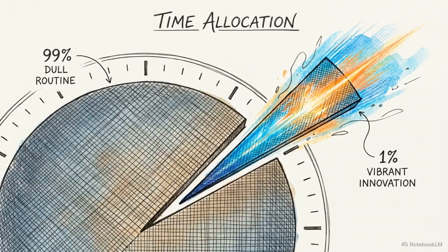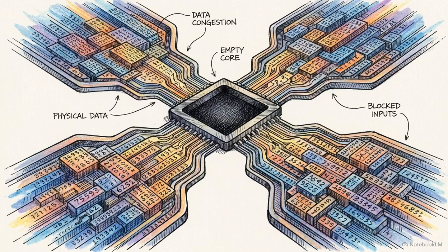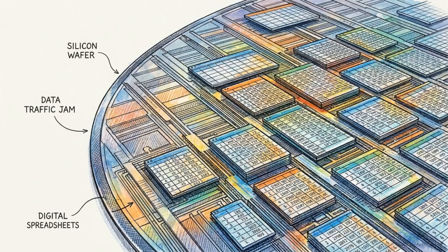During this entire operation, the compute cores are actively calculating for roughly 1% of the wall clock time. The standard algorithm is heavily memory-bound. It starves the fastest components of the GPU, forcing them to wait while massive grids of numbers are shuffled back and forth across the silicon.